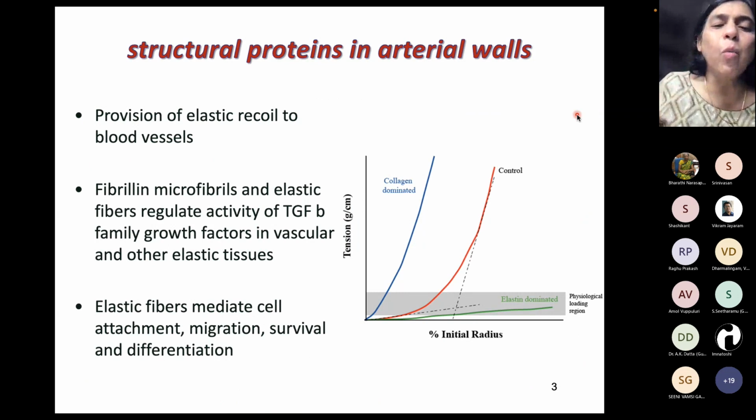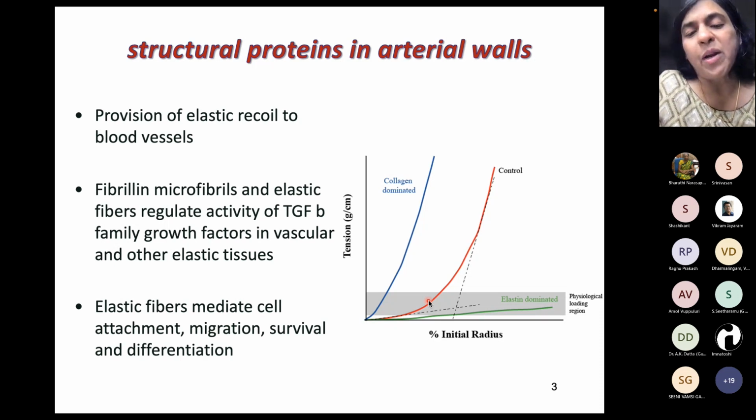So to tell you a little more on why we chose the kind of materials we did, early work has showed that the properties of artery-like tissues, including skin, lungs, and so on, are very nonlinear. So they typically have these J-shaped curves. What is very interesting about these curves is the initial region is dominated by rubber-like proteins, and the end part where you have strain stiffening response is dominated by collagen. And we were interested in both these aspects of how these things contribute to the mechanics of hydrogels.